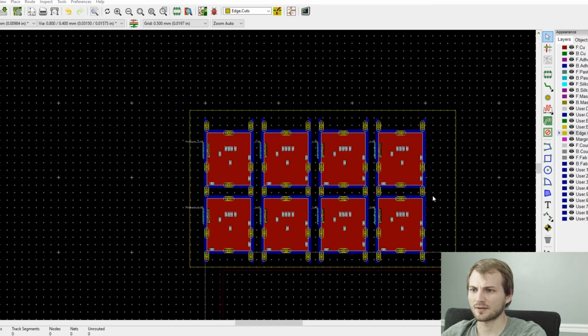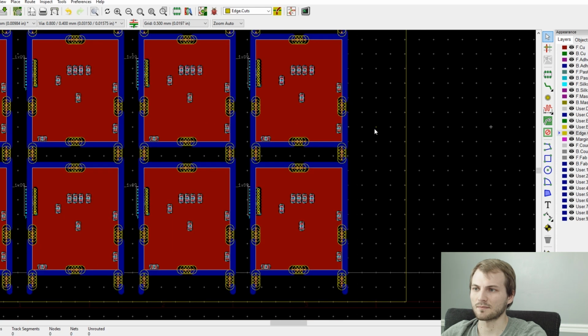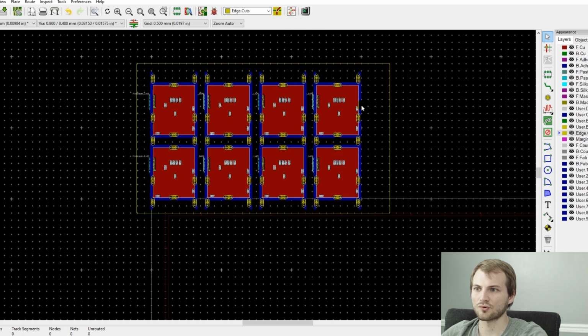So now that the tabs are extended, when you go to break this, you basically start breaking down on the short edge of each side. So you break this edge, this, and this, and now you have individual strips of the PCBs, and then you just have to break this center horizontal part and then your board's completely depanelized.